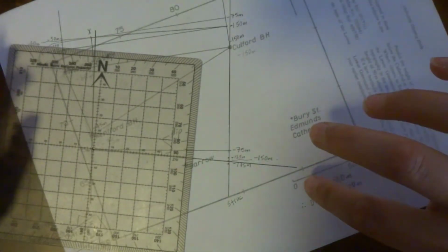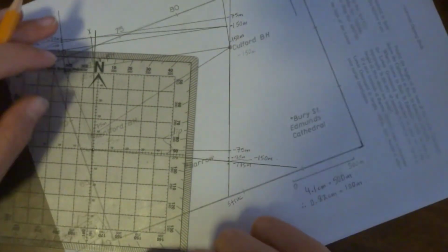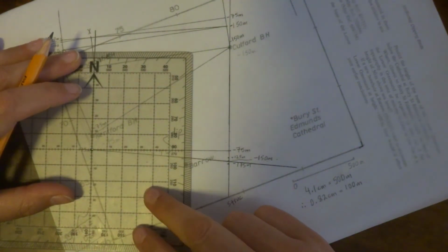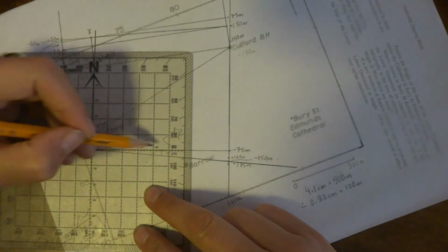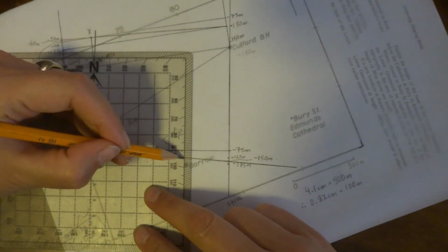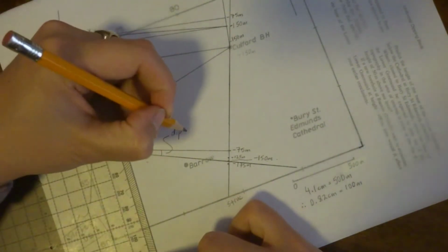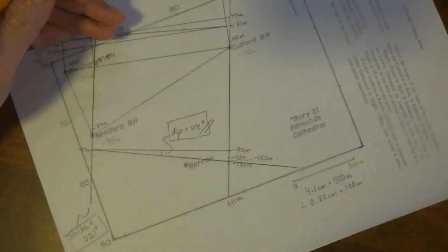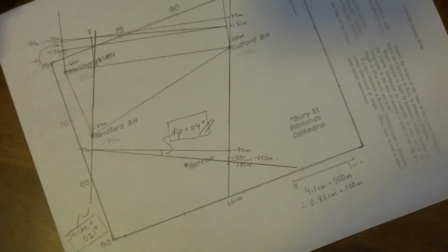We know we're using a vertical scale equal to horizontal scale, so the angle will be equivalent to what we measure with the Douglas protractor. So here we have our strike line, that 0 degree dip, and then we count down from there. So it's about 4 degrees. And there we go. That is our dip.